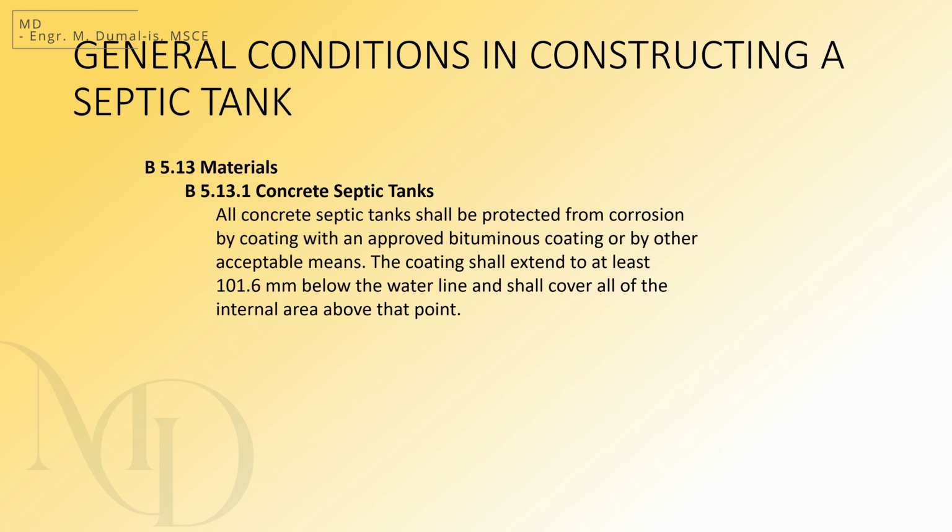To prevent corrosion, it is also very important to waterproof the constructed concrete or masonry water tank. In section B5.13, it mentions tanks must be waterproofed specifically using bituminous material.